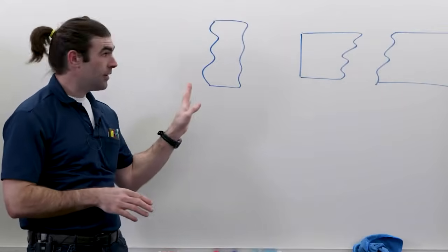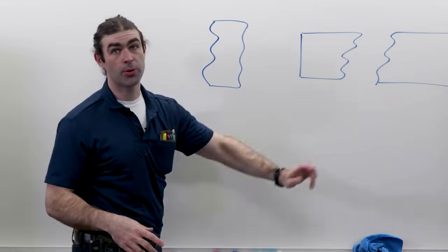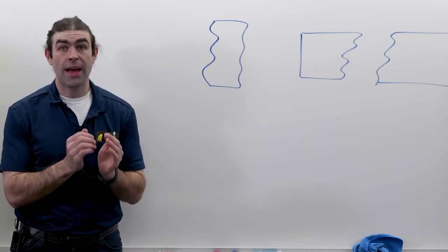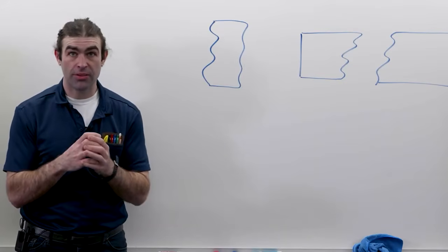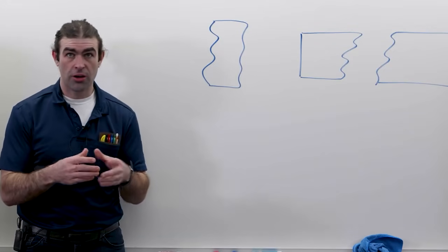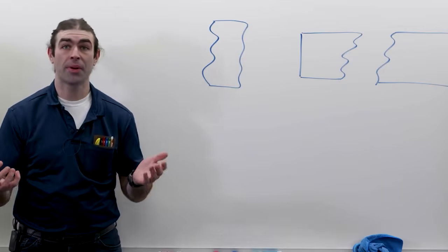So I've got a pin, and then I've got a hole, okay? They both came in with a lot of variation. If we wanted to know what the actual mating envelope of the pin is, we would collapse a cylinder on it. Think about putting a drill chuck on this and collapsing the drill chuck until it makes maximum contact.